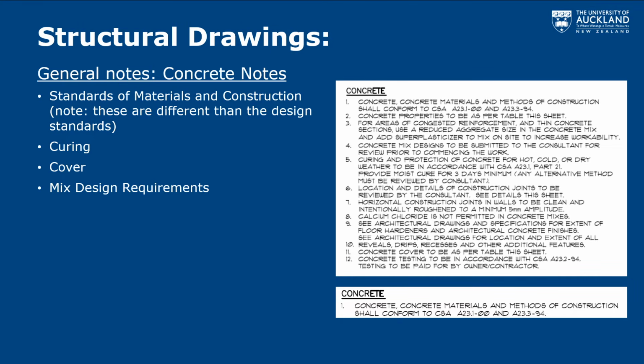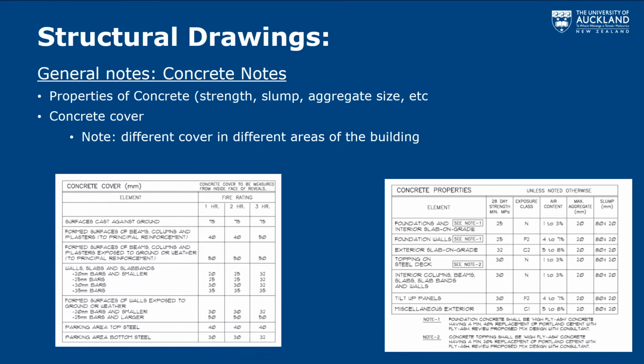so that it comes up to proper strength. Other things are around concrete cover and mix requirements. And around those two, with mix requirements, you can see over here in the image on the right, we're going to specify the f'c, which is the strength that the concrete cylinders would come up to after 28 days. And keep in mind that the higher the strength of concrete we have, the more cement, which equals a higher cost.